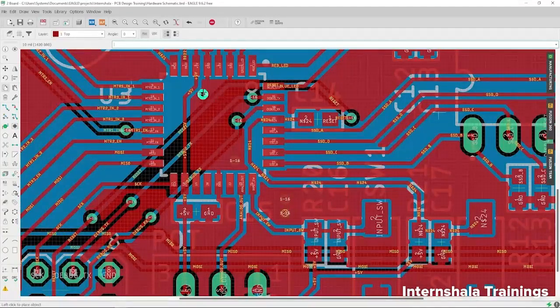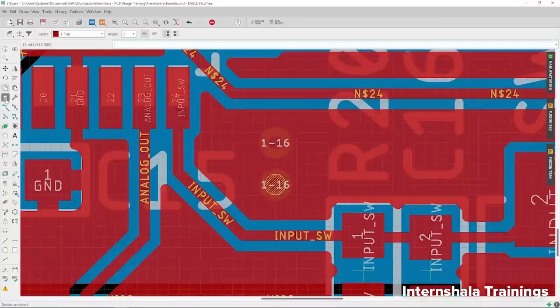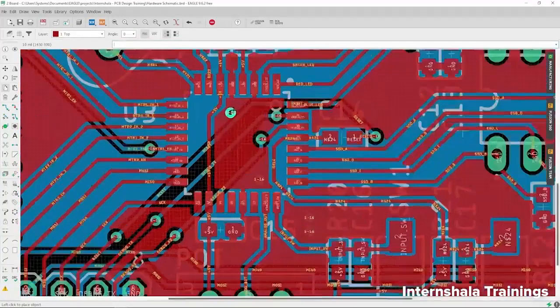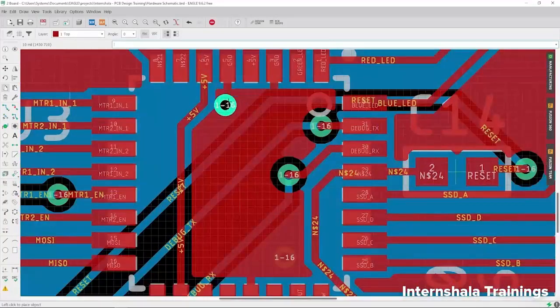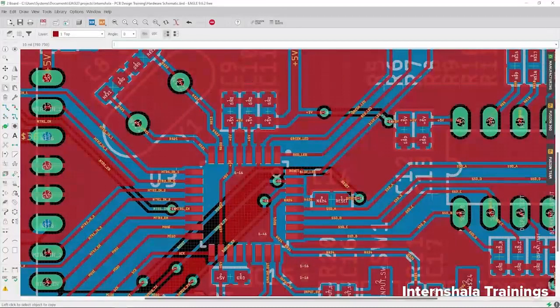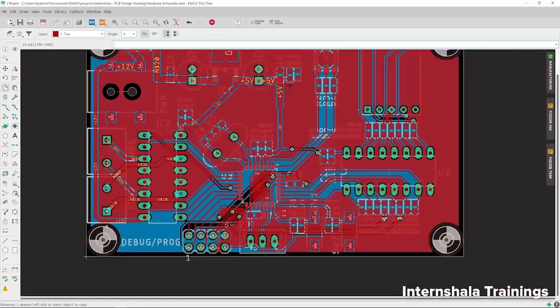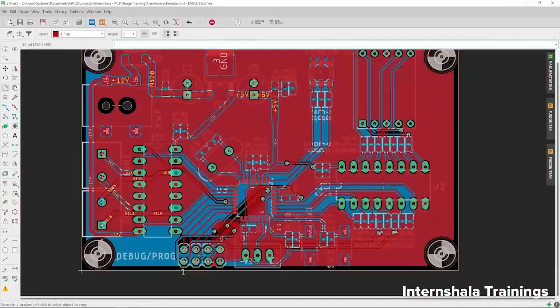Okay, so this yellow warning is there because there are multiple wires on top of each other. So I will just copy this one and later I will place this wire here, and still it's not resolving the issue. So if I click on rat nest, alright, let's try to connect this plane on the bottom layer.